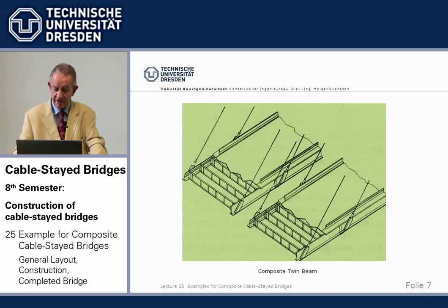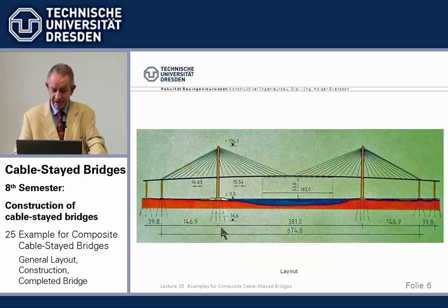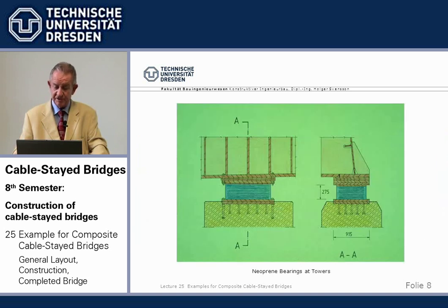Well, the good thing normally is, originally, very often, the fixed point was here, and the beam was hung into one tower. That makes the towers unsymmetric, oversized. And so we wanted to anchor it at both towers at the same time so that horizontal forces are taken by both towers similarly. And what we chose here was we used rubber bearings